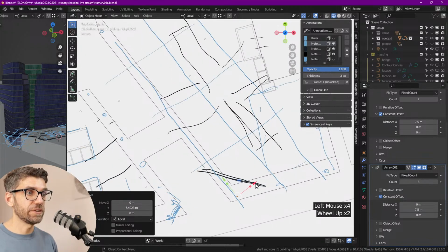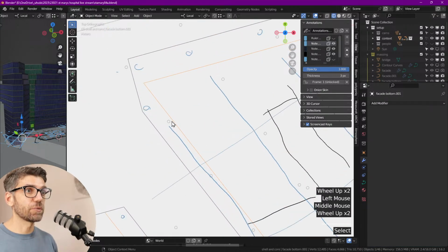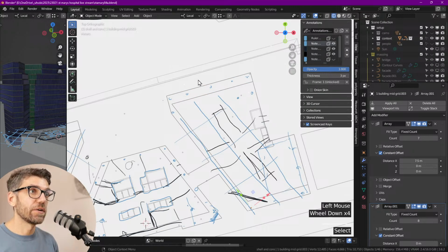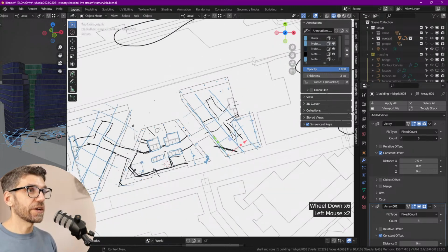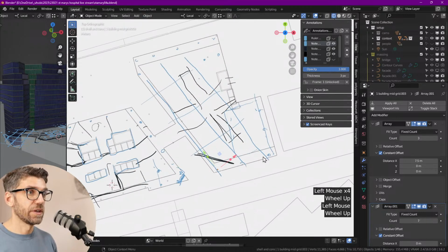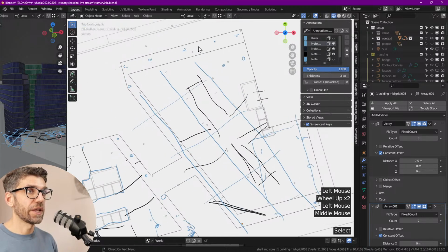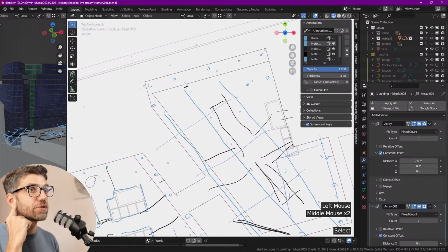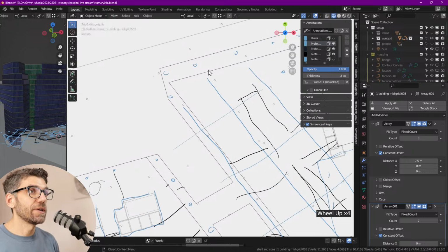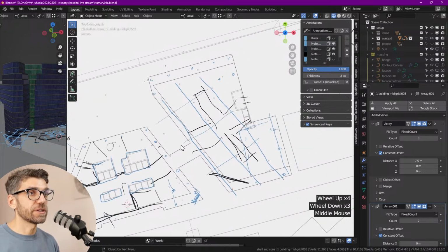Okay, to something like that. So that is 1.5 meters away from our external edge. So that works fairly well. Now in the other direction, we have only something like this here. That's the base of our core, right? And now we'll have to modify a couple of columns so they're in the right position. How are we going to do that with the columns to keep them parametric? Because at this point, we definitely don't want to go in there and put columns everywhere. We want to keep this as seamless as possible.